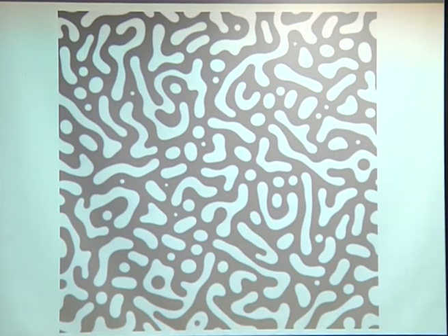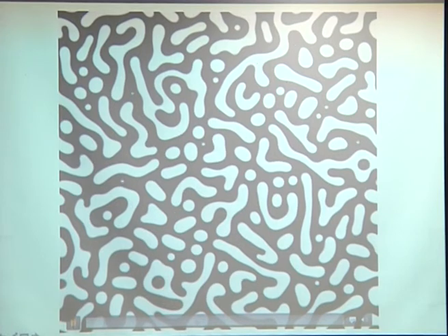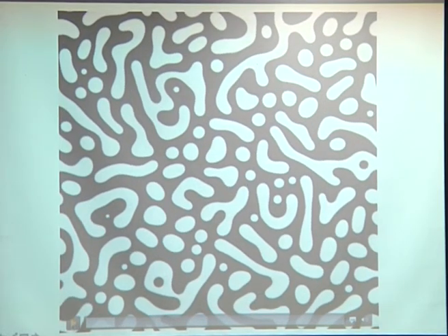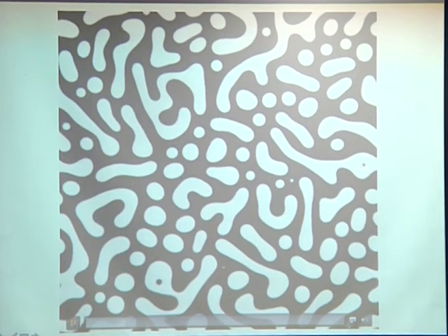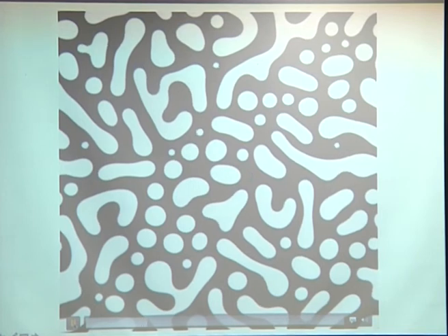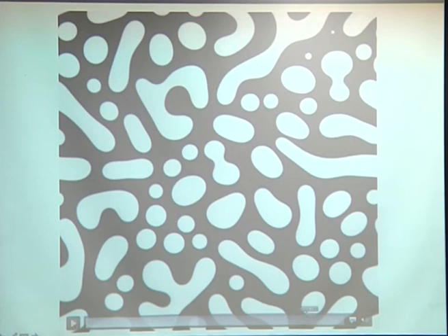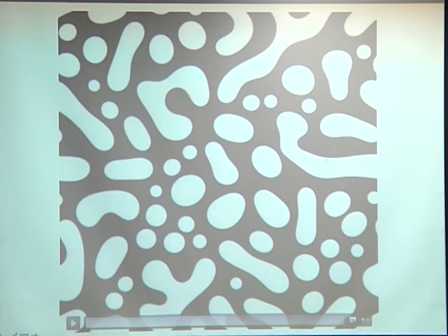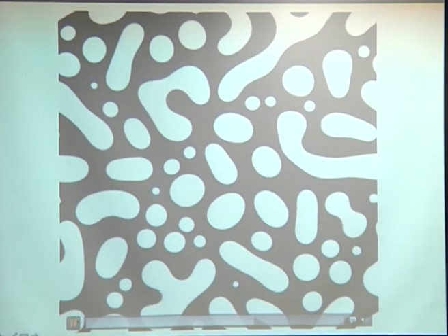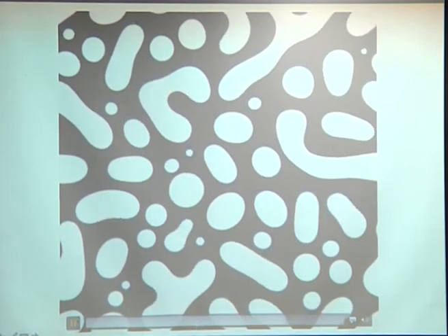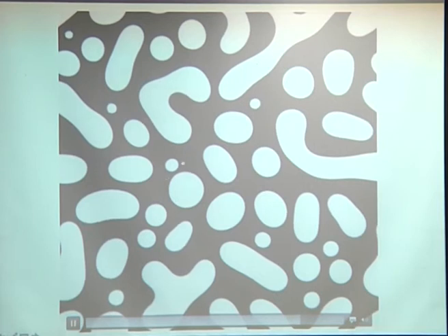People don't use it. The other thing I want you to notice is that you can have merging. Do you see it right there? So there are examples of merging maybe in this region. I don't know, we'll see. No, they're coarsening away. Sometimes they merge, sometimes they coarsen. You see it? Yep, there it is. You see it up there? That was an example. The other thing that the phase field method does, and the technical word for this is topology transitions, is that it allows for merging. It allows for particles to disappear.